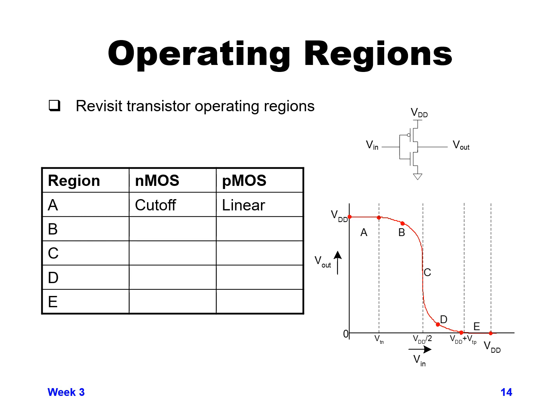And that's because our output voltage is high enough, or close enough to VDD, in that region that the PMOS is no longer in saturation. So the PMOS is fully turned on, but the drain to source voltage for the PMOS is close enough to VDD that the PMOS is in linear region.